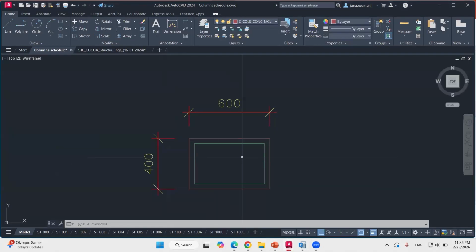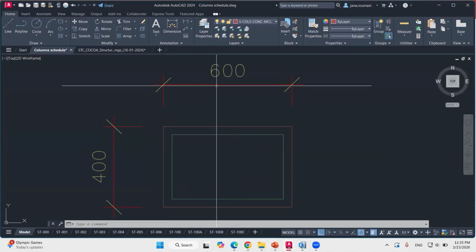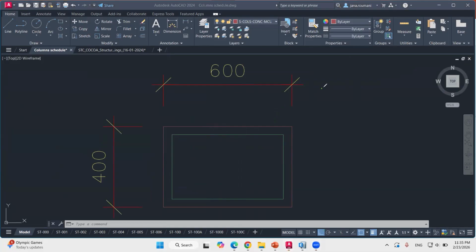So one school says that if I have a width of 200 millimeters, I place 2 bars. 300 millimeters, I place 3 bars. Starting from 400 and above, I place 1 bar less. So 400 millimeters is also 3 bars. 500 millimeters is 4 bars. Okay, 600 millimeters is 5 bars, and so on. 700 millimeters is 6 bars, and so on.